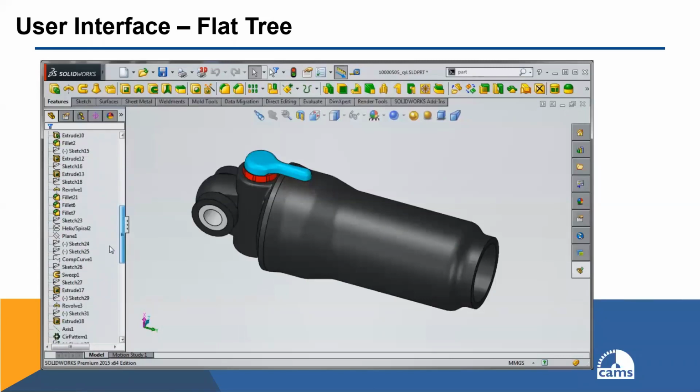And that will pull out all of the hidden sketches. Let you look at all of this information, see which sketches still need to be fully defined, okay? And to further analyze what was done, how it was done, and how complete it is, okay? A great tool when you have to clean up somebody else's mess.